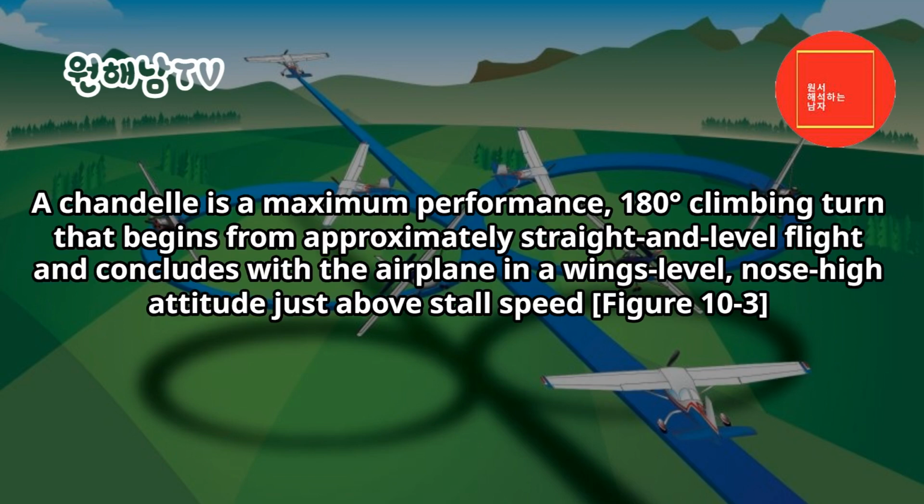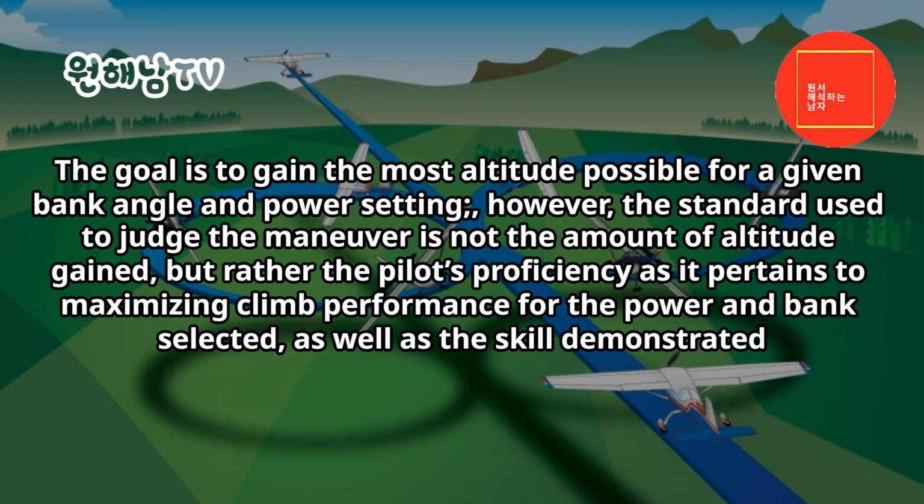Chandelle. A chandelle is a maximum performance, 180 degrees climbing turn that begins from approximately straight and level flight and concludes with the airplane in a wings level, nose high attitude just above stall speed. Figure 10:3. The goal is to gain the most altitude possible for a given bank angle and power setting.